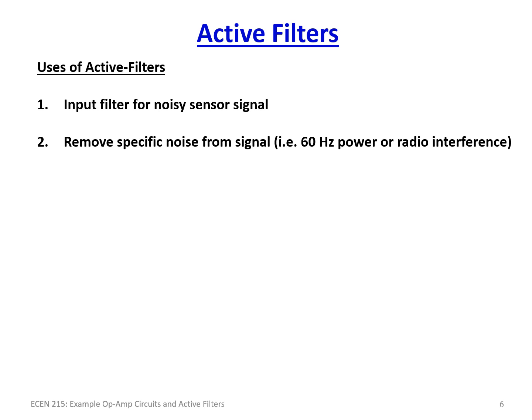Or if you're getting specific radio interference, if your circuit is for whatever reason very susceptible to cellular band radio frequency, for instance, and it's causing problems with whatever signal analysis and processing you're doing, then you sometimes are going to need a specific band reject filter for that.